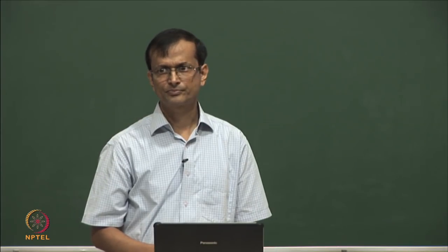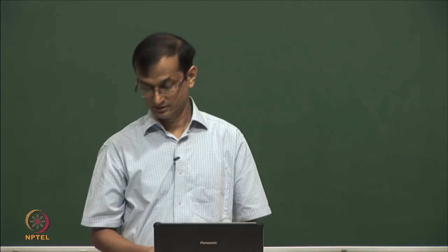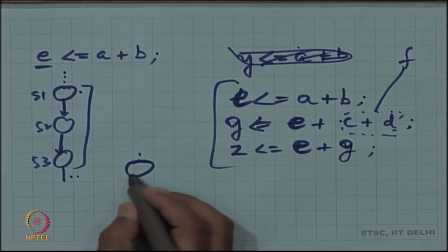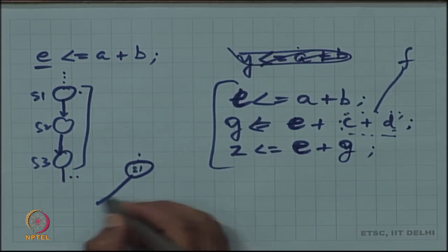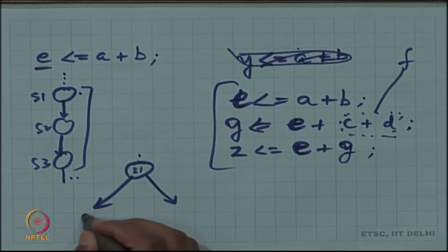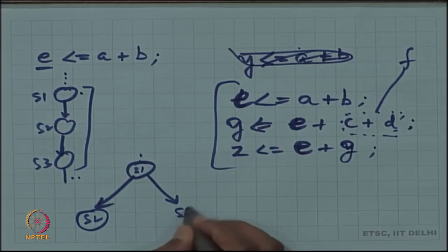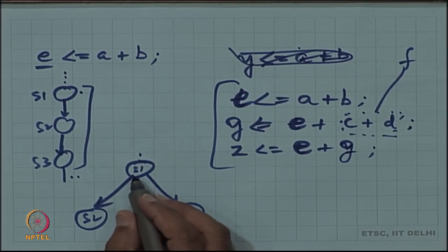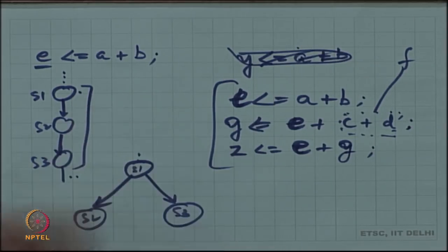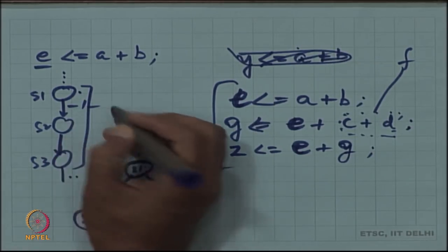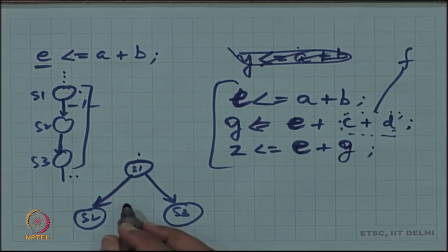Multiple states, I mean, one state leads to multiple states. Right. While these were linear structures that we saw so far, the structure might not be linear, right. The next step may not be obvious. So far the next step was obvious and therefore that condition was actually do not care here. But it may not be obvious, you may be dependent on something that is the result of the computation from the data path, right.